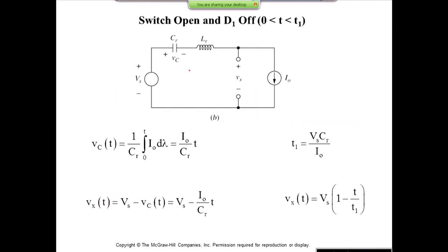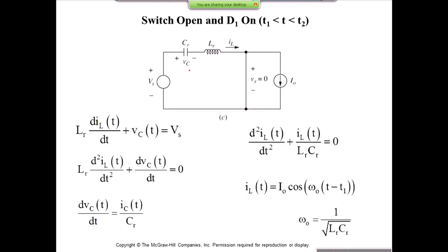Unfortunately, these topologies provide ZVS or ZCS, which is good, but at the same time, the analysis is more complicated. The voltage transfer ratio is hard to obtain, and the operation of the system is dependent on a lot of parameters, for instance, the value of your load, or the switching frequency. So these are the disadvantages.